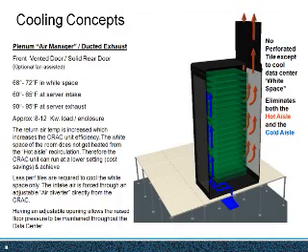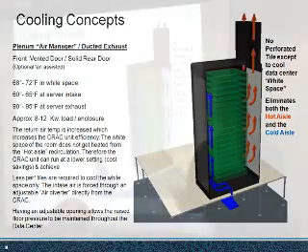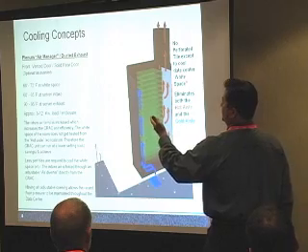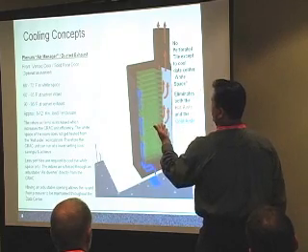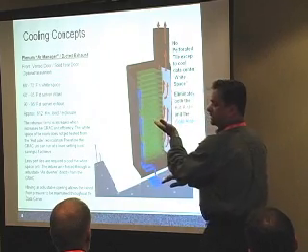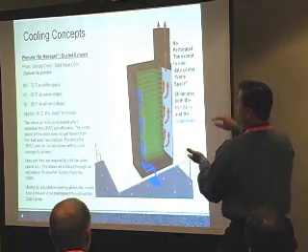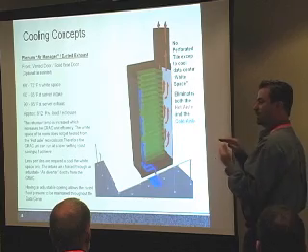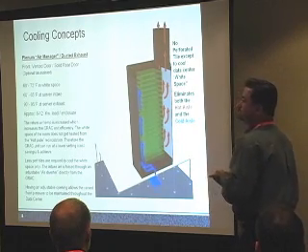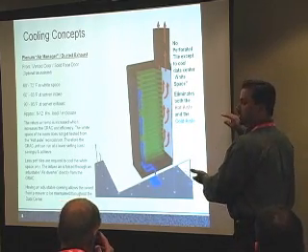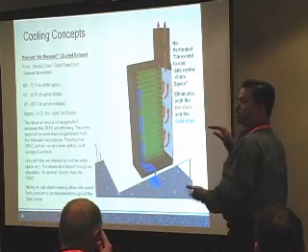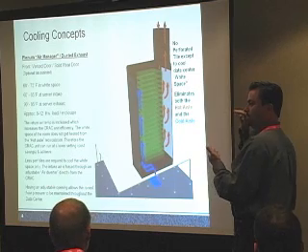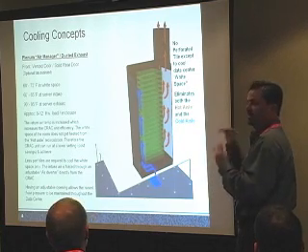So now we have a plenum air manager with a ducted exhaust. So now what we get is 68 to 72 in the white space, and now 60 to 65 at the server intake. So those two temperatures are now reversed. So now I'm able to get a bigger delta T across my equipment, so I have a greater heat load that I can install in this enclosure. I have a greater cooling capacity of this enclosure because I have a cooler temperature, and yet my exhaust temperature stays the same.